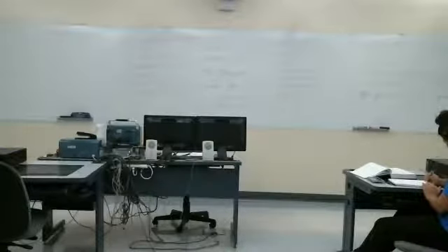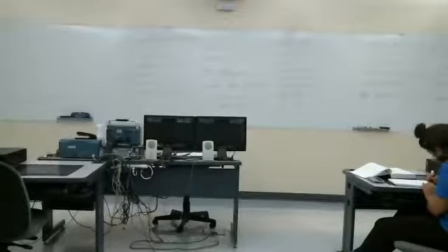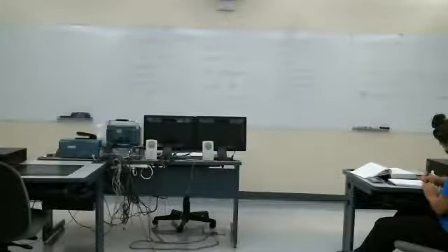Now again, an impulse is kind of this fictitious signal. I can approximate it in the lab. I can't generate it, but I can mathematically find out what it is. Theoretically, I can calculate what the impulse response is in my system, and we'll figure out how to do that. Generally, if x of t is u of t, the output is what we call y step, the step response.